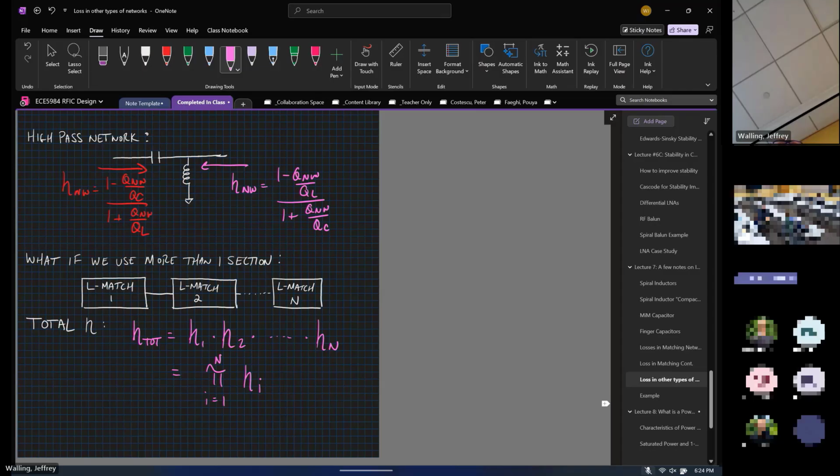So people do make calibration structures, but it's less common to do something like that because the area penalty is pretty severe. You can imagine just adding an inductor just for the sake of calibrating out the losses is not a good use of silicon. So we also will use EM simulations just to estimate what that is.